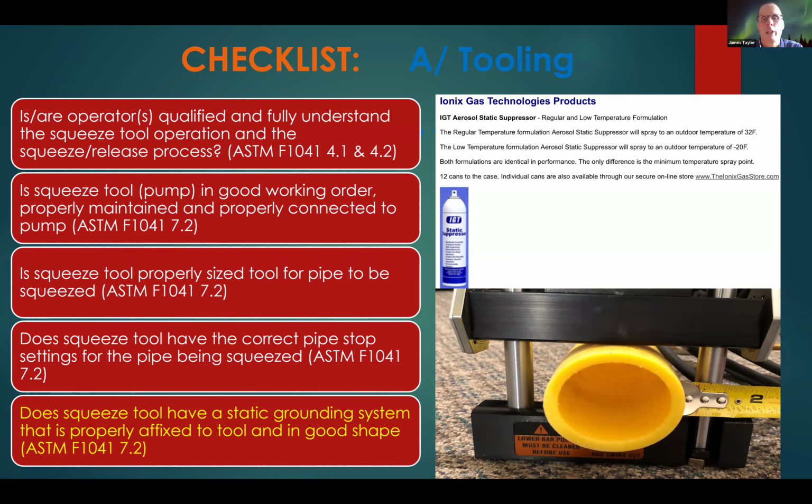So what you'd want to do is take your gauge plates on the side of the tool, on our tool or any other manufacturer's, and make sure that their over squeeze protection settings are listed on there per your data stamp or print line on your pipe. Make sure they match. So if your pipe is 2 inch 11 on your pipe, you better make sure that one of your over squeeze protection settings has 2 inch 11 on it. So they match. Okay. Thank you.